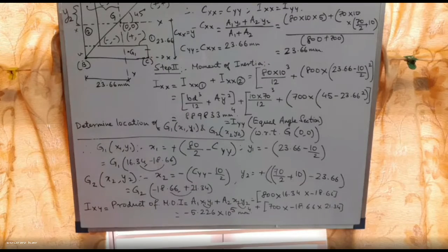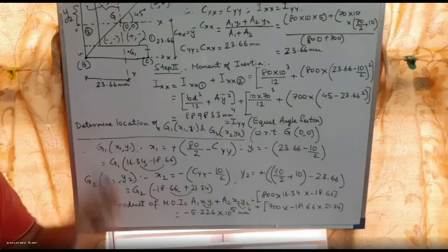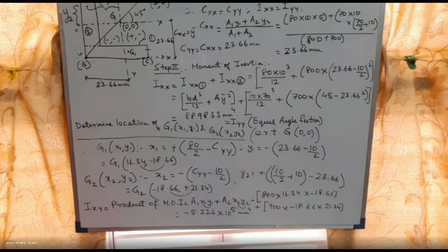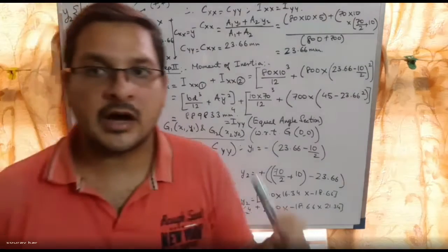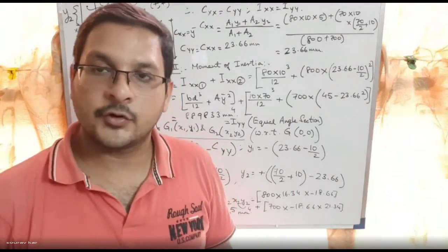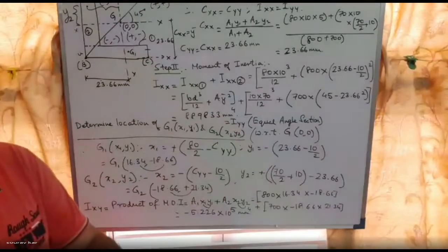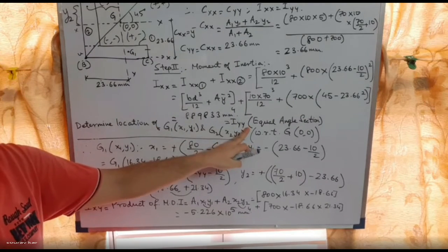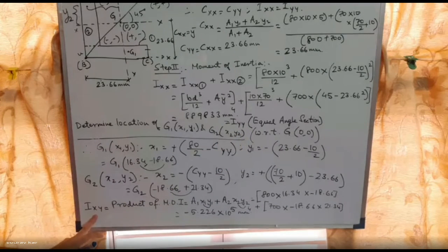This is my step 1. So I have got the principal moment Ixx, Iyy, then Ixy. This is very important, because all these parameters will be required to find out the next items. So now I have to find out IUU and IVV. To find out IUU and IVV, I will require IXX, IYY, and IXY. That is what I found out.